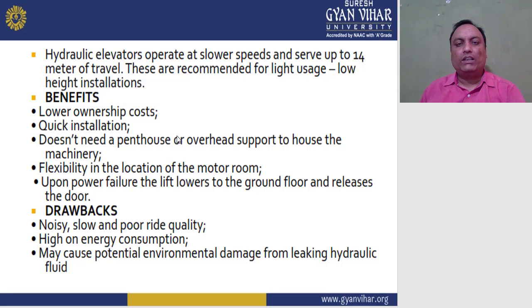So we go to the hydraulic elevator. The hydraulic elevator operates at a slower speed and serves up to 14 meters of travel. These are recommended for light usage and low height installation. Benefits: lower ownership cost, quick installation, and no need for a penthouse or overhead support to house the machinery, and flexibility in the location of the motor room. Upon power failure, the lift is lowered to the ground floor and releases the door, right?